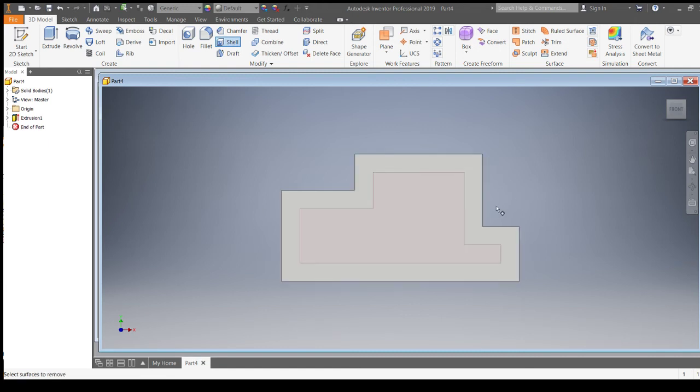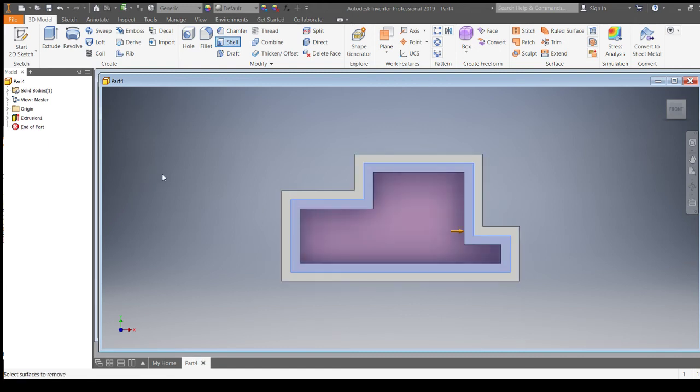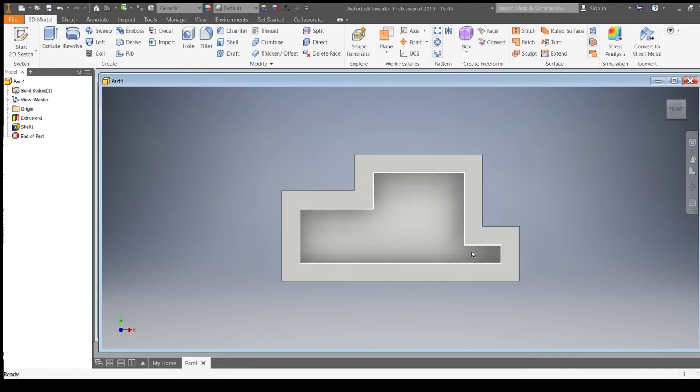Now if we do both, click on the front face, you'll notice it has extended the borders and also come inside, so you'll see that our smallest cube is still incorporated into the shell, but it's much smaller because rather than it just being shelled to the inside or to the outside, both are being shelled, which creates sort of I guess a best of both worlds, you could call it, sort of.